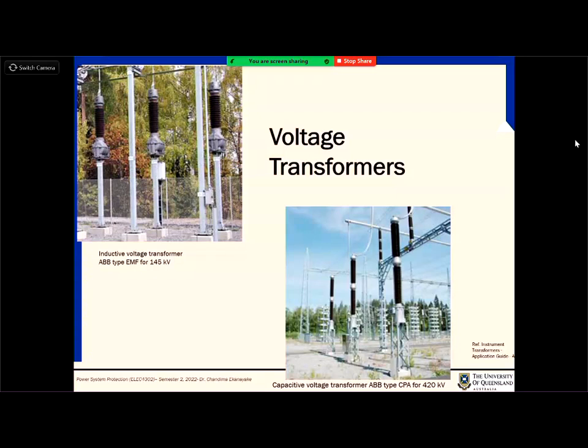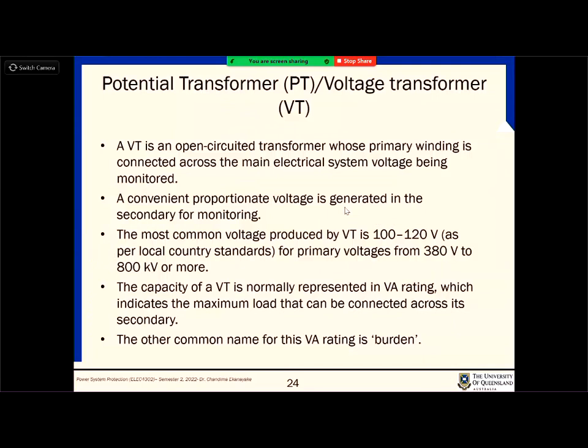If I recall, these VTs have only one connection from the supply, and the other end is grounded. Typically these VTs measure the ground to phase voltages. There are certain VTs which measure between the phases, but most commonly between the ground and the line, because the voltage levels are lower than between the lines.